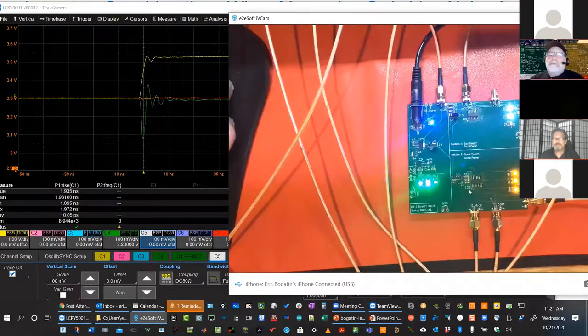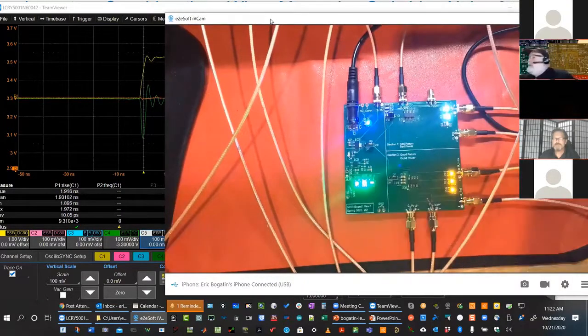It's only by measuring on die that we're going to see the actual switching noise, which is a form of power rail crosstalk to all the other IOs. This is switching noise. This is what we're trying to minimize by using decoupling capacitors in close proximity to the IC. Okay, and this is also an illustration of, I'm going to zoom out so you can see my system here.